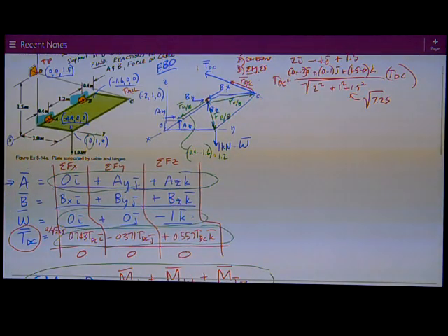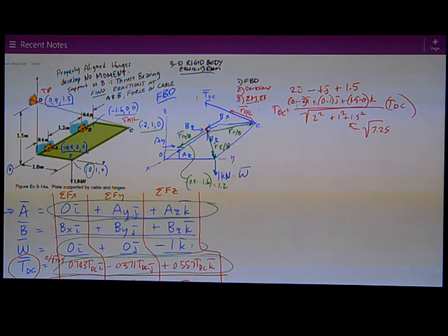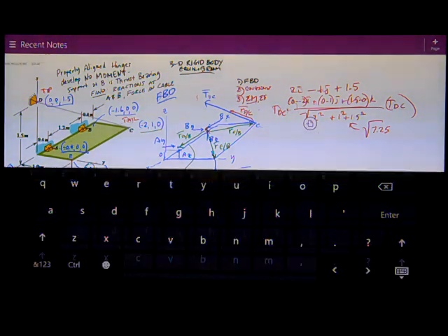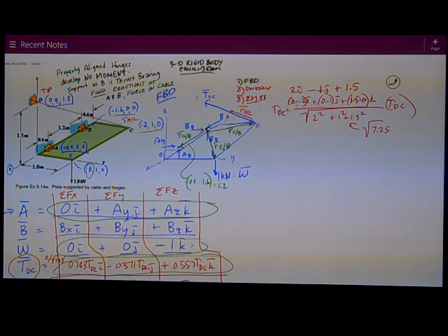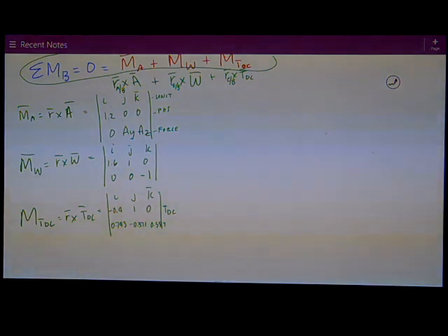Finally, I have this position vector from B to C, RC over B. I've got -2 minus 1.6. So that one's equal to -0.4. And then I've got 1 minus 0 for the y component, and 0 minus 0. So the middle row of this one is -0.4, 1, and 0.